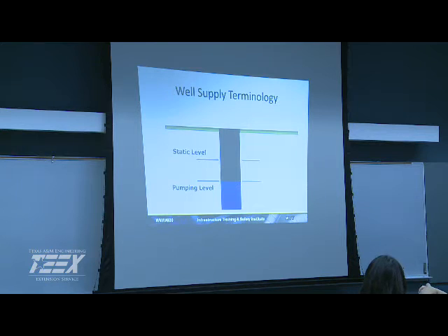You know, in dry periods, when you're not getting much rain, it shouldn't flow, and when you have a lot of rain, then it should flow a lot. Most of ours, at least in this area, have such high variance that if it's artesian, it's always flowing. If they're not pumping it down, it's going to overflow.